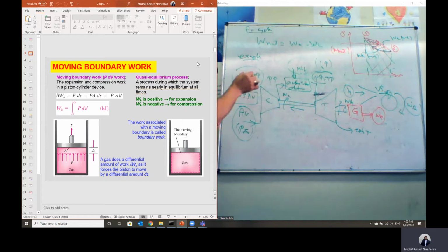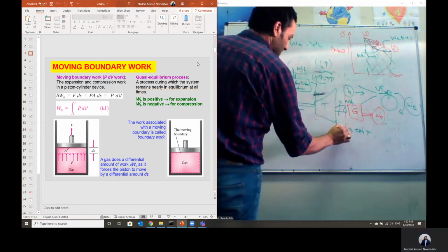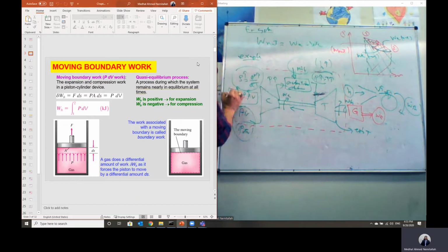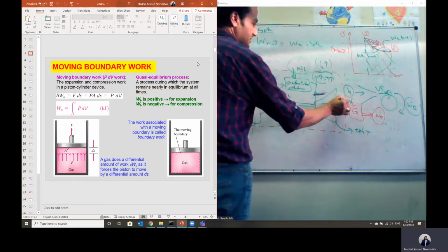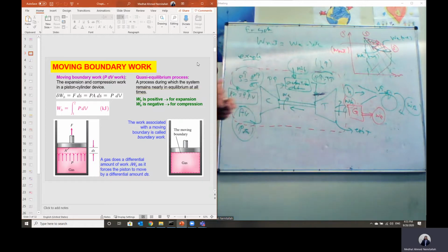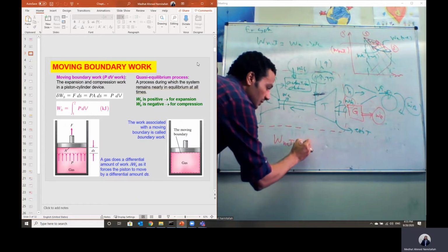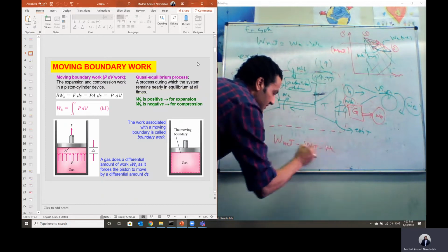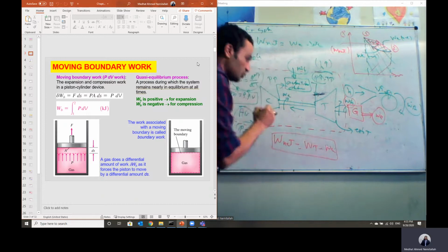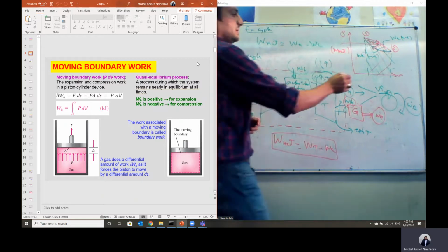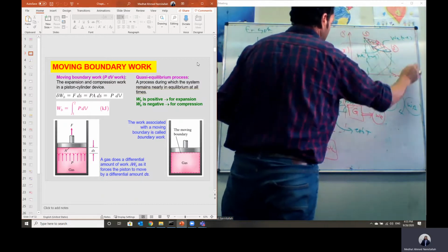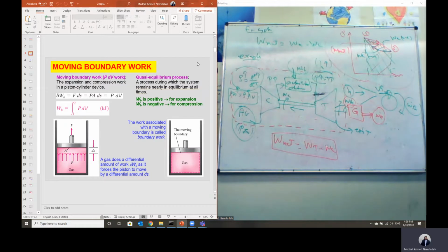Okay. But for this gas turbine to generate continuous shaft work, it has to work on a cycle. We have to repeat this process. And in this case, the net work of this cycle will equal the work of the turbine minus the work of the compressor in this case. And this cycle can be represented on the PV diagram by this curve.